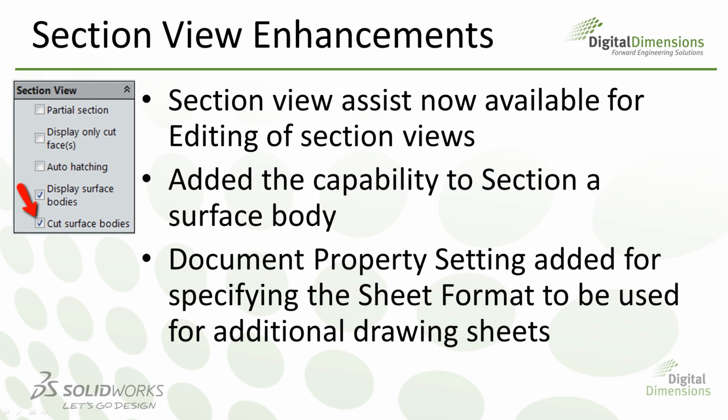And then the next thing to mention here is there is a new document property to accommodate your next sheet title block. So in other words, in the past, when you generate a new sheet, well, for starters, SOLIDWORKS added a setting that turned off showing the sheet format dialog on Add New Sheet, which always confused me, so I always tell my classes where to turn it back on, because most companies use a separate title block for Sheet 2 anyway, so having that toggle was kind of confusing.